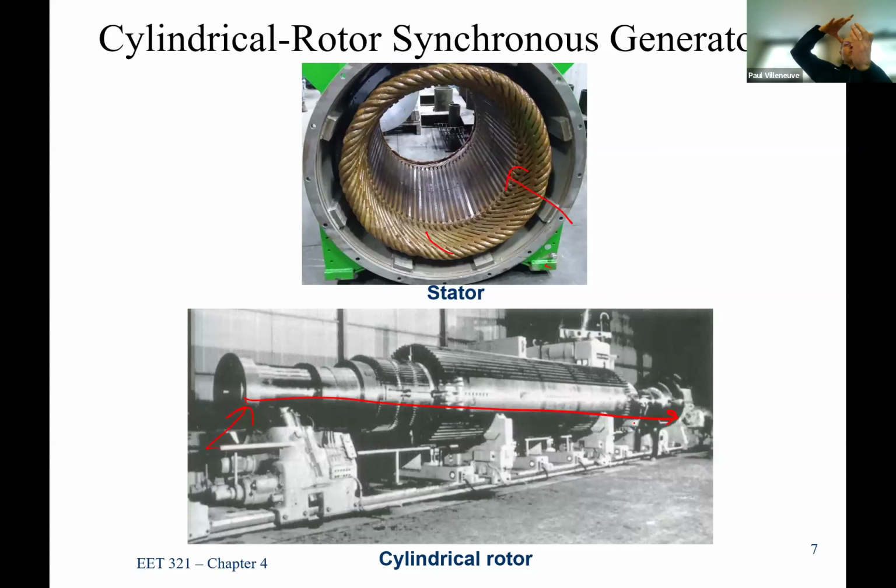Otherwise, the rotor bow inside the generator shaft could actually impinge upon the windings inside the stator of the generator. So you'd have to get it rotating, or you're going to have to jack the unit up and do all kinds of different things. Because that air gap is going to be tight. You don't want a big air gap. It's not like you can just have a variable air gap. It should always be as small as possible.